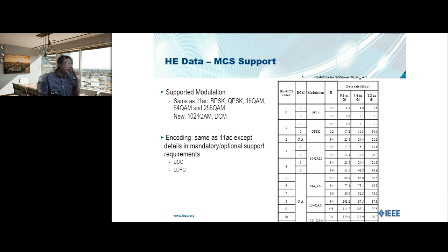There are a lot of detailed rules. I will not go over them. You can go to the spec. For example, if it transmits in 20 megahertz or above bandwidth, you have to use LDPC. If you use 1024 QAM, you have to use LDPC. There are a lot of details. Feel free to read the spec.